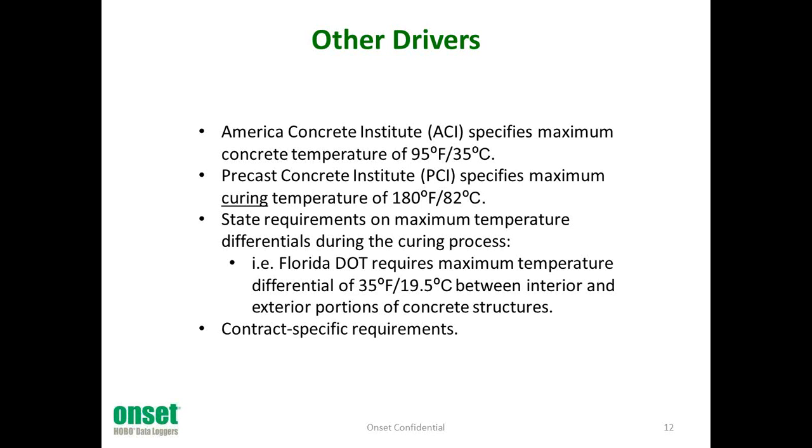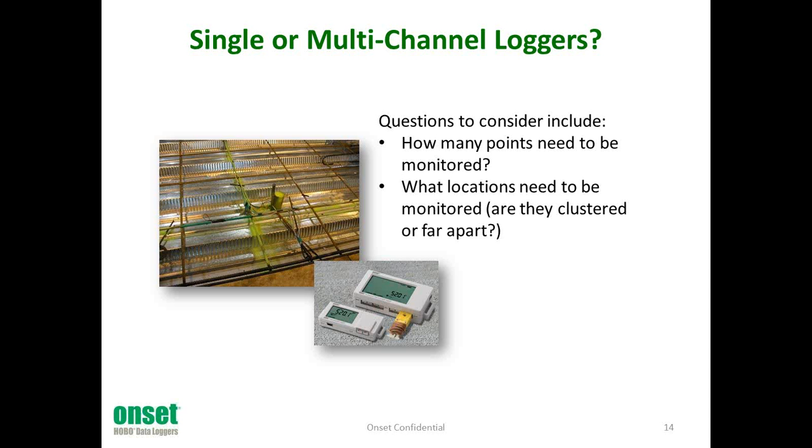Thermocouple data loggers provide a cost-effective, simple way to take in-situ measurements in concrete as it cures. They provide users with around-the-clock measurements and reporting of temperatures at critical locations. These data loggers accept a wide range of thermocouple probes and can be configured and installed in minutes, making them extremely versatile and user-friendly. The LCD display readout allows viewing of current live temperatures and indicates if high or low threshold alarms have been exceeded. This is convenient for spot checking your concrete conditions during the curing process. There are also different models to choose from which allow for a single or multiple thermocouple inputs.